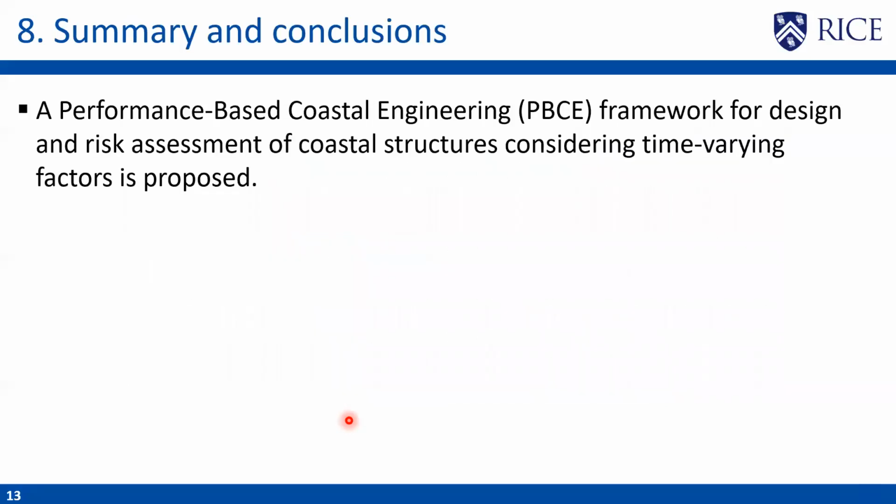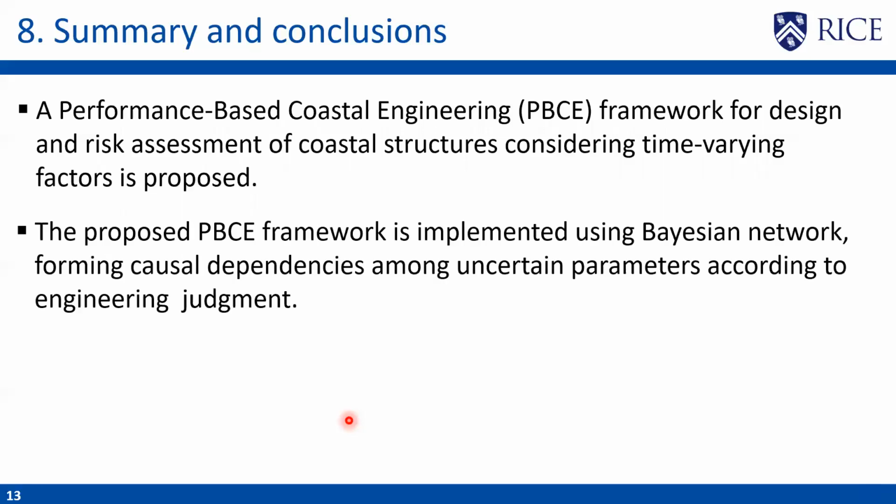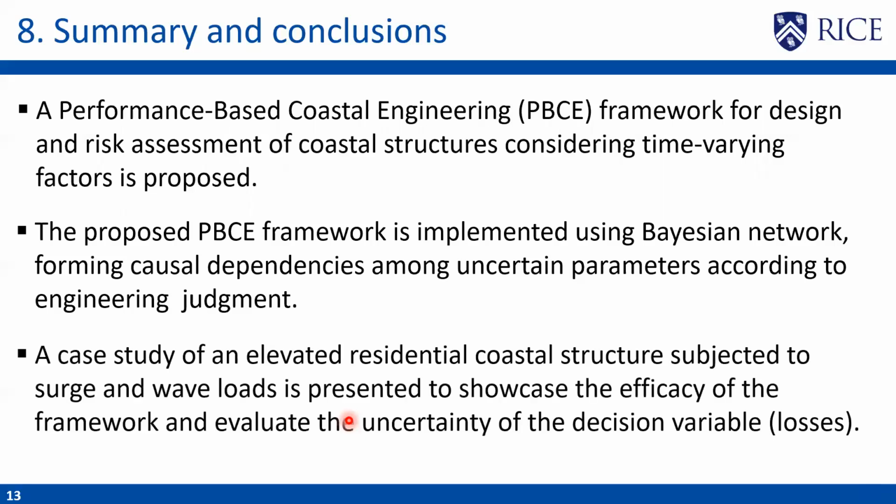Some summary and conclusions of the work. A performance-based coastal engineering framework was proposed for design and assessment of coastal structures, considering time-varying factors. The proposed framework is implemented using Bayesian networks, forming causal dependencies among certain parameters that we can form according to engineering judgment. And then a case study of an elevated residential coastal structure subjected to surge and wave loads is presented to showcase the efficacy of the framework and evaluate the uncertainty of the decision variable, that in this case was the losses.